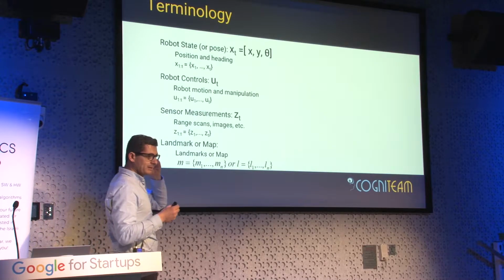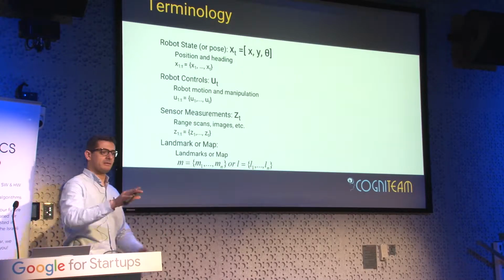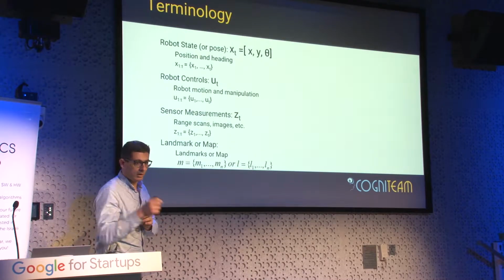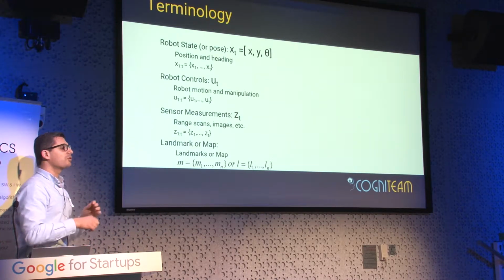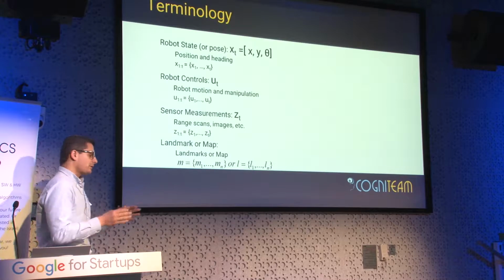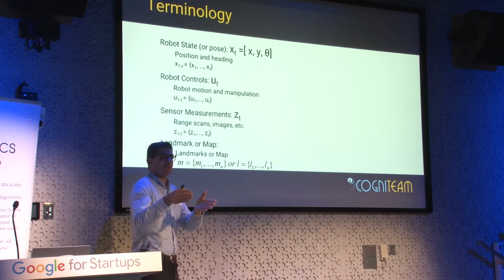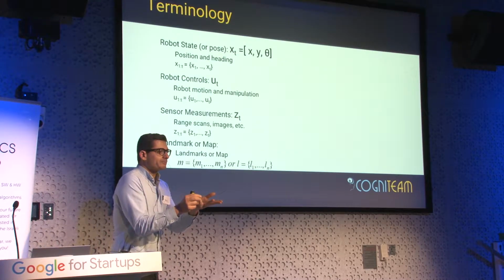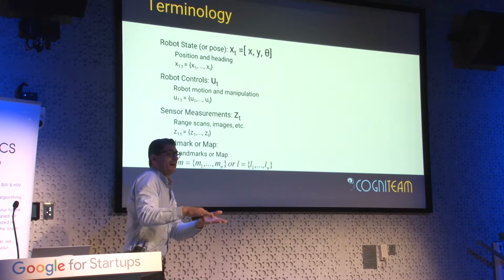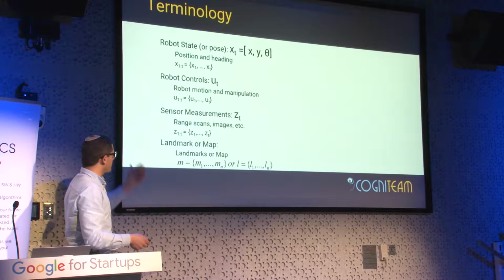Let's denote xt to be the location of the robot at time t. The location is x, y, and theta. x1 is the location of the robot at time 1. ut is the motion model, the motion of the robot at time t. So it starts in a specific place, then in u1 it moves a delta x, delta y, delta theta. You can get it from, somebody can help me? Odometry. Okay, from IMU, movement by IMU. You can get it by the IMU or odometry or something like that.